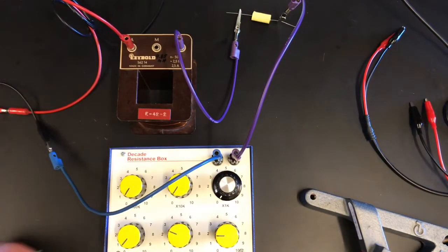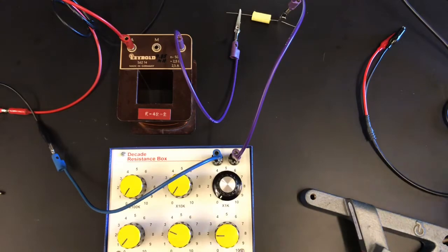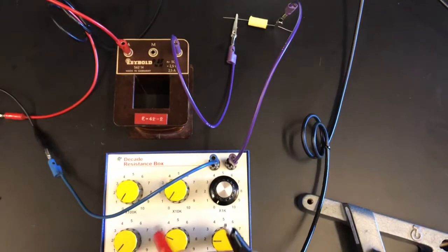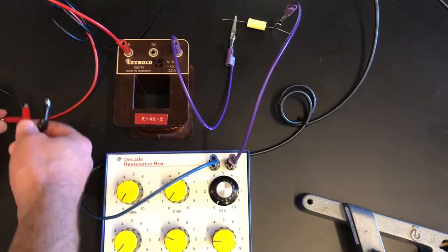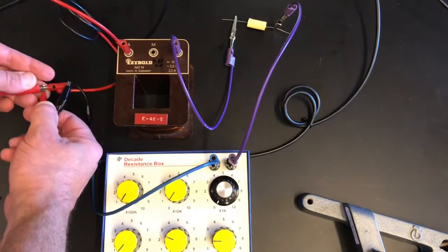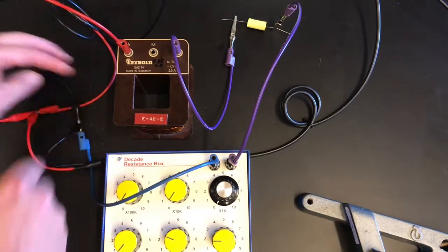So I know this might be a little bit of a mess visually, but I just wanted to show you setting it up. And then what I'm going to do next is take my oscilloscope channels. The oscilloscope is just off screen, up there. And the first channel, channel 1, is going to be VO. And so that's going to be just the output of the function generator. I can do that on this cable over here. Just put in the red on the red and the black on the black.